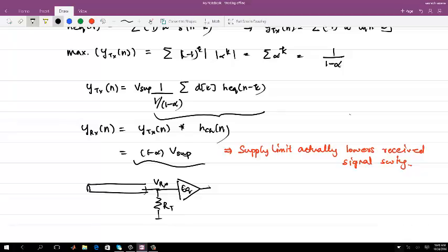Here you see that I have used only one single alpha. Here you can have a larger alpha also, you can try. But again, you will always be limited by the final supply swing. Still, here you have more headroom. If I have a 1 volt swing here and the received signal is only 10 millivolts, I have room to gain more.